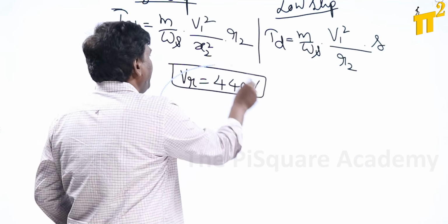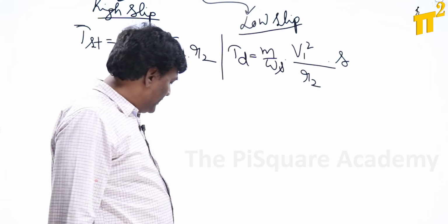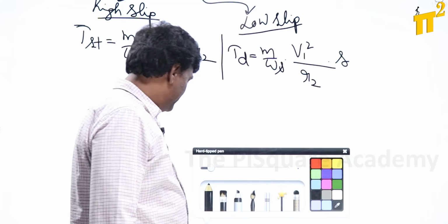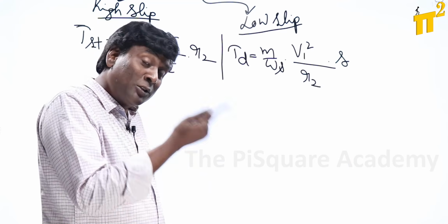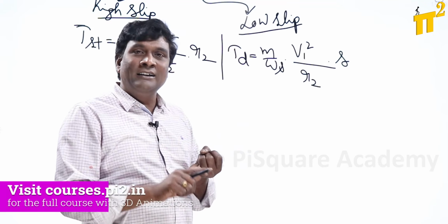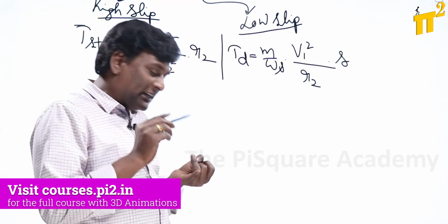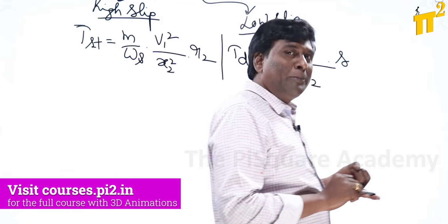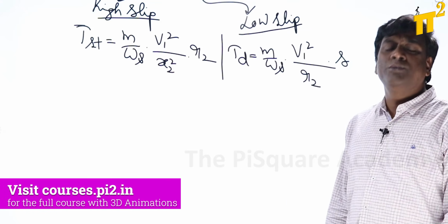Next, if I think of running conditions, they will give you clearly whether there is a constant torque requirement for the load or not, because running conditions will be decided by the load. Starting torque will be decided by the machine, pull out torque will be decided by the machine, but running torque will be decided by the load. Who are you to decide?